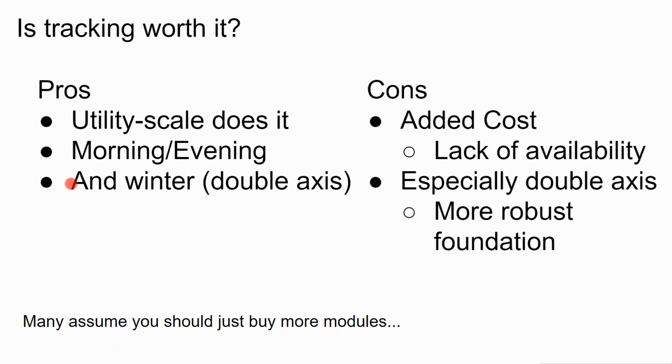Now, whether you get more production in the winter and summer because you're doing east-west tracking versus north-south tracking, it doesn't really matter. Either way, or even if the tracker was in a northwest or a southeast orientation, being able to track over one axis is still going to result in boosted production no matter how you cut it.